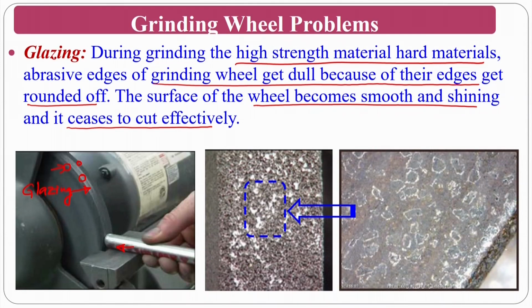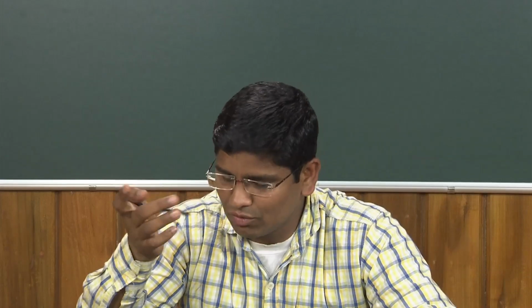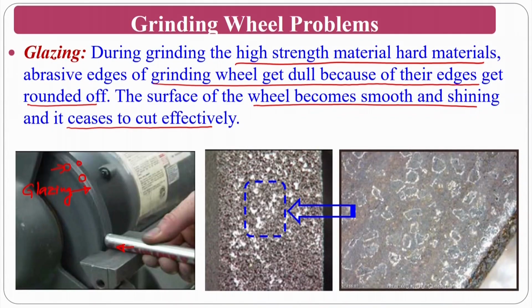You can also see practically how it looks, because of the hard grade versus hard workpieces, the surface becomes smooth. I mean, not the workpiece surface, the surface of the grinding wheel becomes smooth. That is what you can clearly see in this wheel. If you exaggerate, you can see here how the abrasive particles become dull and inefficient. Okay, this is called glazing.